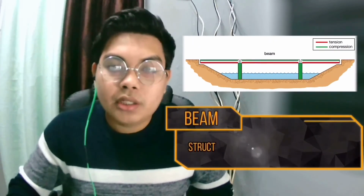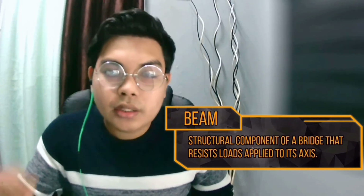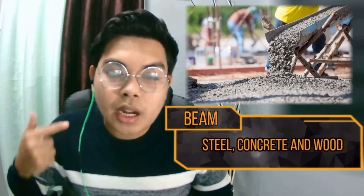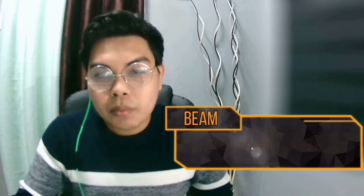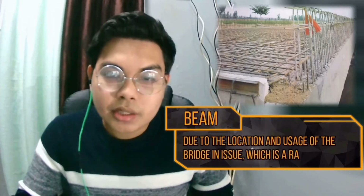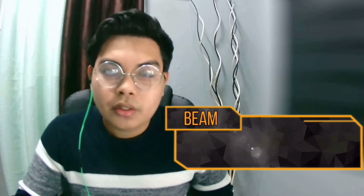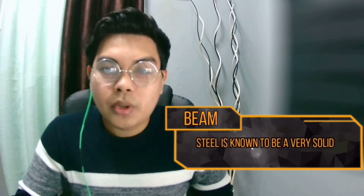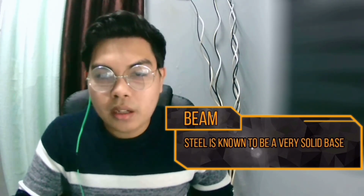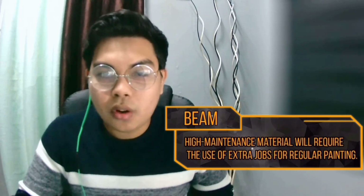A beam is the structural component of a bridge that resists load applied to its axis. There are three materials used as beam base, which are steel, concrete and wood. In this case, we recommend that the base be concrete, specifically reinforced concrete, due to the location of use of the bridge in question, which is a railway bridge. This is because despite steel being known as a very solid base, this particular beam is used frequently by the train, and the fact that steel is a high maintenance material will require extra jobs for regular painting.